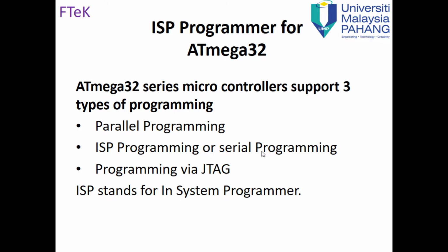We are going to use what's called ISP programming. The ISP programmer, the one that I already showed to you, we are going to use for Atmega 32. Atmega 32 series microcontrollers support three types of programming: parallel programming, ISP or serial programming, and programming via JTAG. We are going to use ISP, which stands for In System Programmer.